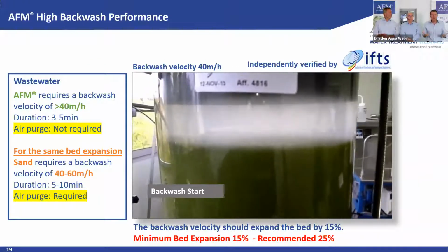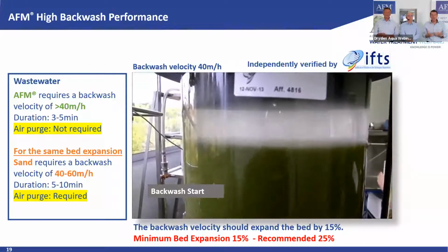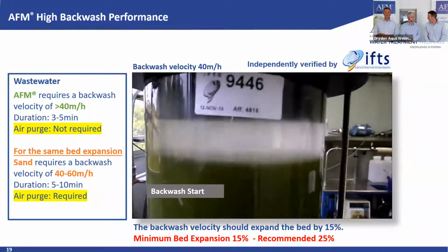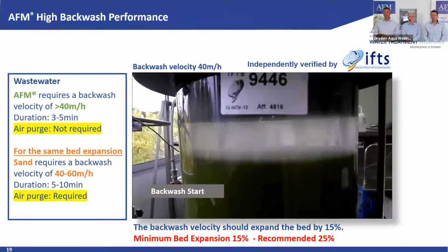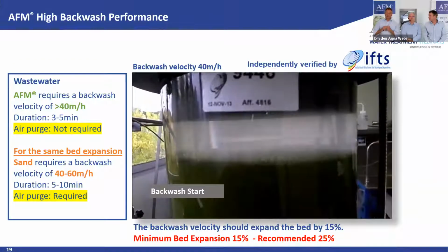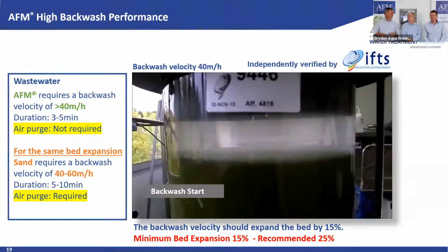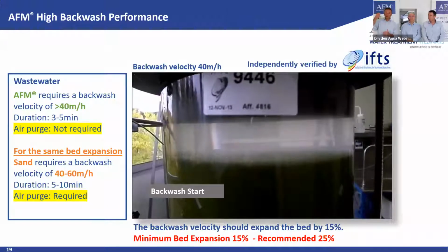AFM, because you have no biofilm, you do not need to air purge. Yes, and this is also why often you have to backwash sand at the same velocity a lot longer, because you really have to rip off this biofilm first with air, water, only water.